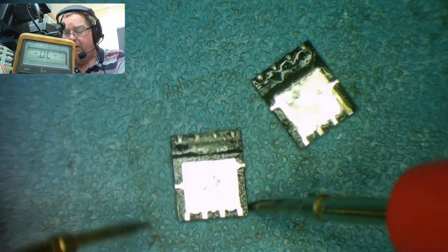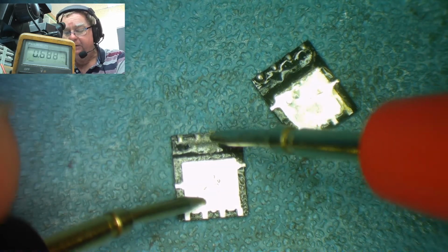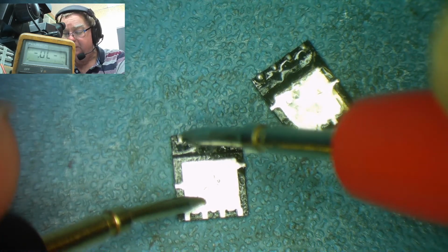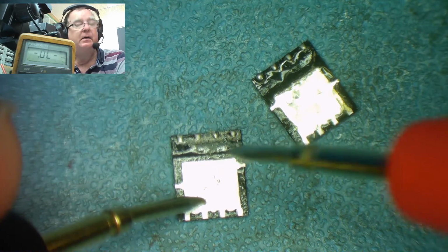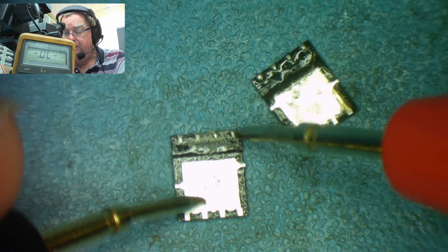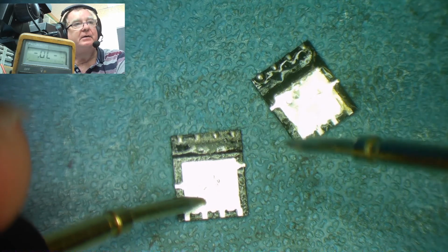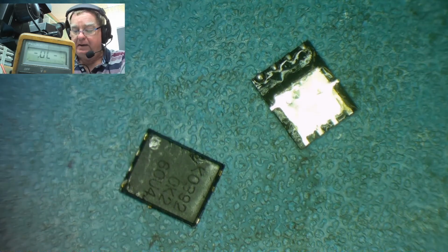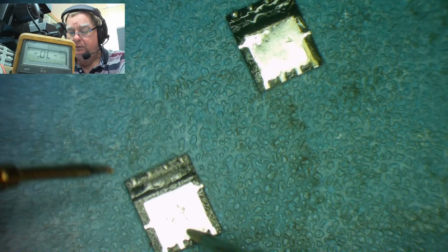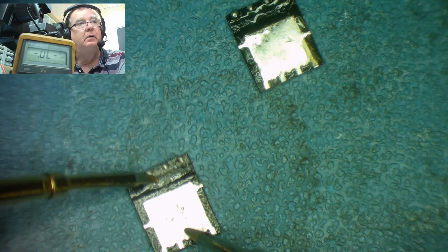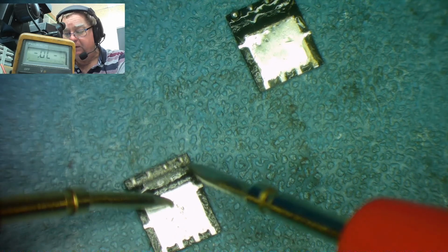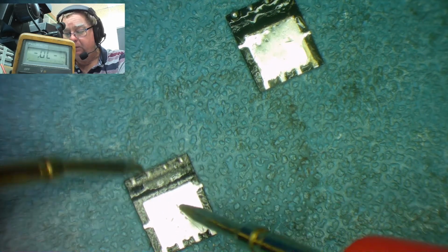Now, if I find the gate and put the positive meter lead on the gate, it'll be one of these two ends. I'm not sure which end. Try this end, yeah? No, that's still the diode junction. It must be the other end. Right, touch that to that, yeah? That should turn this FET on now, and now it should actually look like a short circuit. Possibly discharge it when I turn this upside down. Let's try again. Touch to that one.